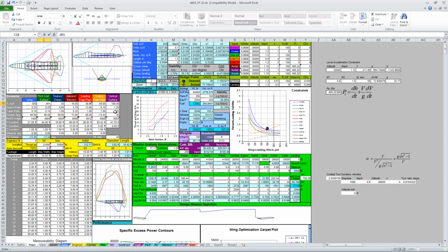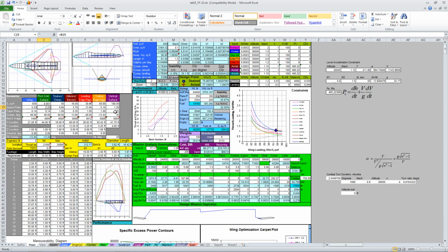All right, here we go. Well, isn't that interesting? The aircraft got more stable. Now, it probably got more stable because the CG moved forward. We removed 1,000, 1,100 pounds, something like that, very far back on the aircraft. And so the CG moved forward, and so the static margin increased.